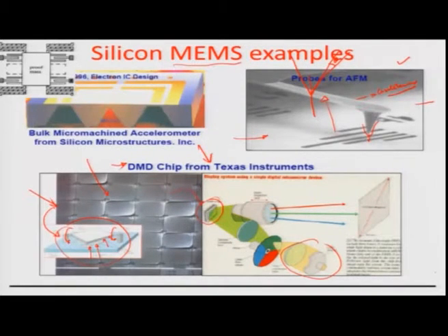This is where the beam gets guided into this particular lens here, which projects it on a bigger screen by magnifying the image. Now, supposing there is a mirror which goes out of place and out of this focus. The small micron by micron dot which is otherwise formed by reflected light into this focus, now being away from the focus, comes as a dark pixel.